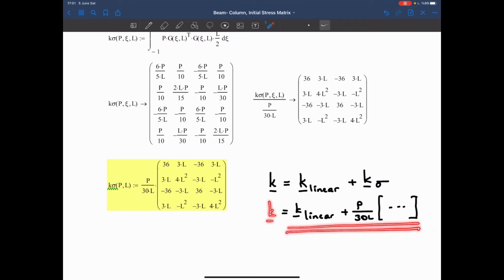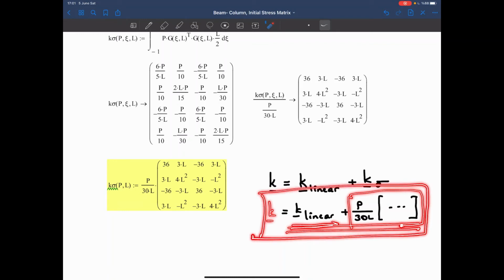And remember that the only assumption that we make to obtain the stiffness matrix is that we consider the length change. So we only use the Green strain definition. We are saying that in this element, the displacements and the rotations are still small. The deformations are small. So the only assumption that we remove from the linear stiffness matrix derivation is the length change due to bending deformation. And at the end of the day, we obtain the following matrix.